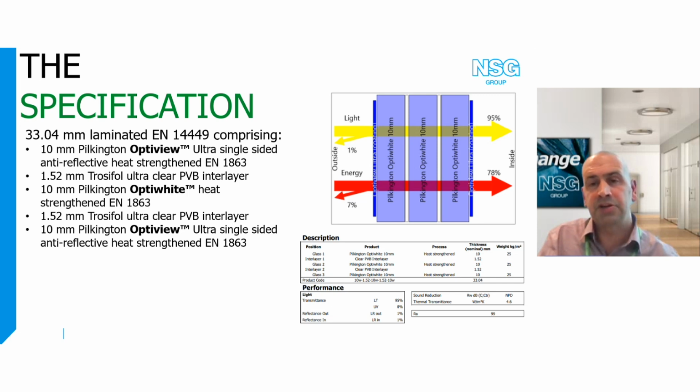interlayers. Heat strengthened laminated was used to provide enhanced individual ply strength when compared to annealed glass, but also providing thermal stress resistance and most importantly post-breakage containment or rigidity in the event one or more plies were fractured, something that toughened laminated glasses cannot achieve unless they were incorporating specialist ionomer load-sharing interlayers.